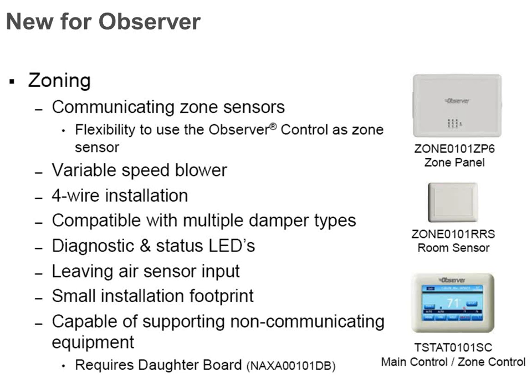Pretty much everything is 4 wires. If you just pull 4 wires to the stats, the sensors, the dampers, everything, you'll be fine. In fact, I would pull 5 wires to everything because I always like to pull 1 extra wire, like some of you guys like to do anyway.